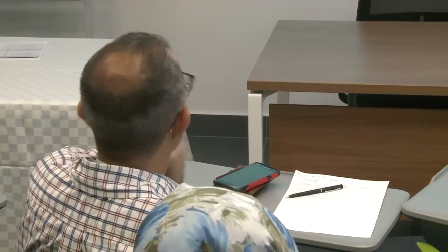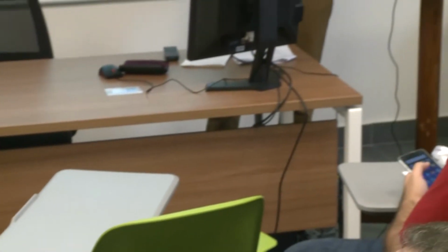So there's one weather station in Eritrea, and that one weather station would suggest that passive design techniques would work in Eritrea. But is that really true for the whole country? In Ethiopia, there are a lot more stations, and there's huge variability, but it still looks to me like you ought to think about passive design in Ethiopia and Eritrea. And I would say Morocco looks like a good one. Argentina looks like there are going to be places where you should really think about designing without using so much energy. Maybe a bit more ventilation, use of glass and controlling solar gain into buildings.